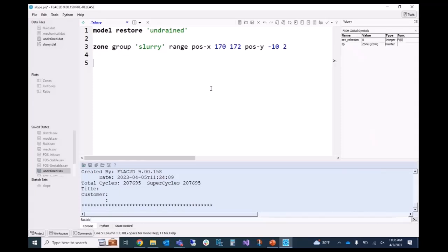So what I have to do here instead is give it with a command. And if I don't give a slot name here, it just goes into the default slot, which is different from the construction slot that the sketch uses. So I'm not overwriting the names that I already assigned. I could be more specific here. I could give it a slot name, slot, something. But I know that it's just going to go into slot default and everything's going to work. Okay. Let's just do that.